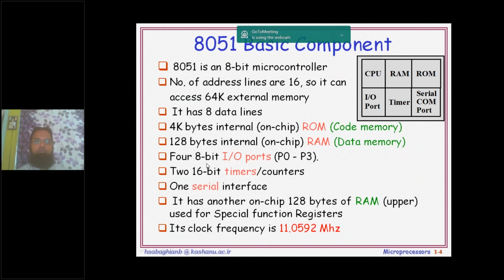And it consists of four 8-bit IO ports, designated as P0, P1, P2 and P3, meaning port 0, port 1, port 2 and port 3. And it consists of two 16-bit timers, and these timers can be used as counters.